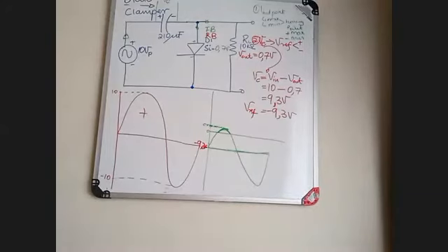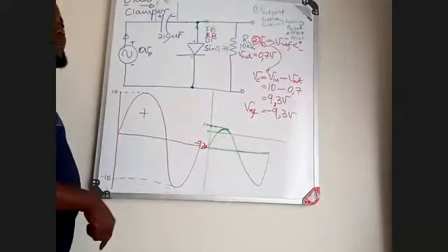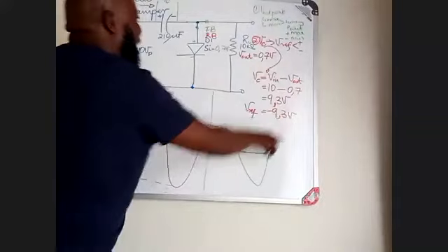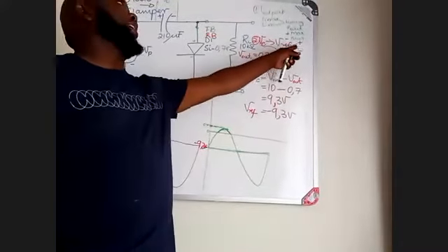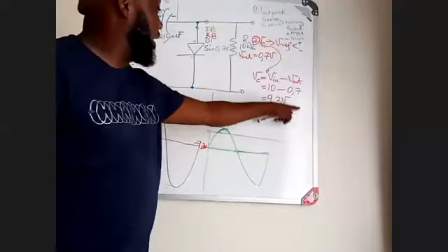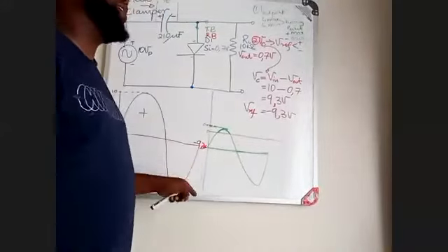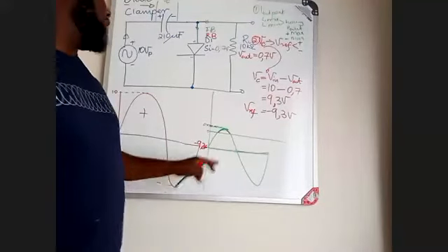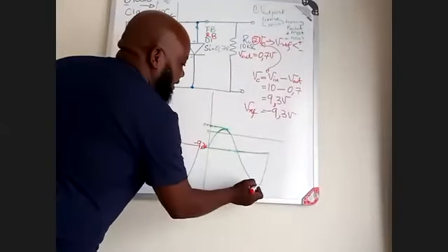When I charge it, it is positive, but the signal shifted as a reference to what? Minus 9.3 volts. That's why I say your VC is your reference voltage. It's either positive or negative, which means in this condition, it is at a negative magnitude graphically, which means it has shifted downwards here. Now, once you get these, then you're going to say, what is the last step?